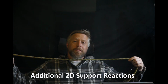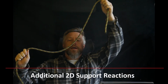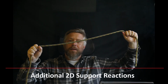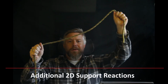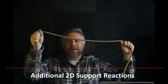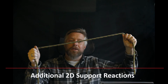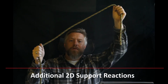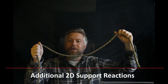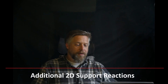Another common support you might see is a rope or cable, and we've already talked about this one. A rope always has to support the load in the direction of the rope. If I have my right hand here and I'm trying to pull my left, if I push up, it's not doing anything. The only way I can pull my hand is along the rope. If I move the rope this way, it's still along the rope. The force has to always be in the direction of the rope. I can't move it up. I also can't push. My right hand cannot push my left hand. Right? The only way is by pulling. So the force always goes along the rope and in a pulling direction.